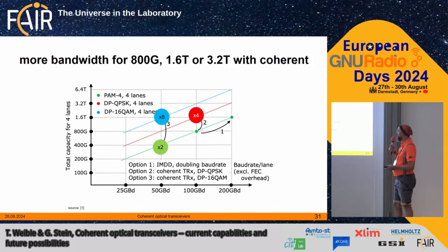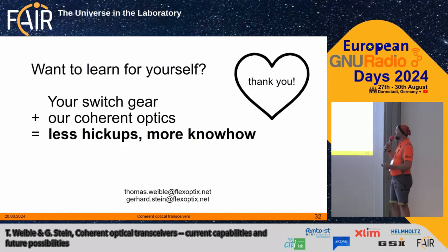Another possibility is to increase the overall frequency, which Gerhard also showed at the beginning, but there are currently definitely limitations on the electrical substrates used for PCBs. We are already at 50 gigabaud, which is a really high frequency, and we can do 100 gigabaud in mass production, which is also used now for 800 gig and 1.6 terabit. That brings me to the end, almost in time.